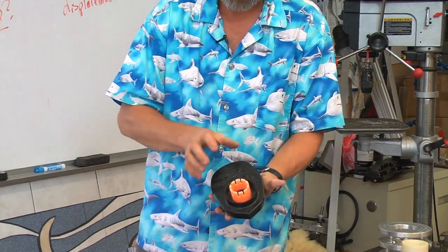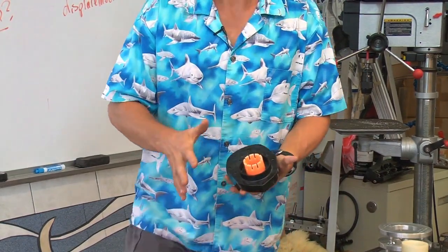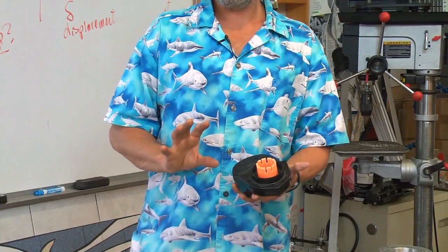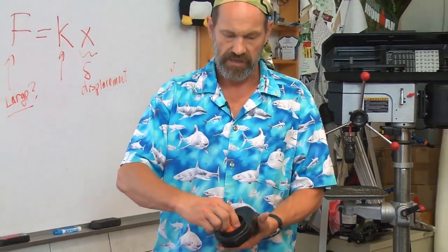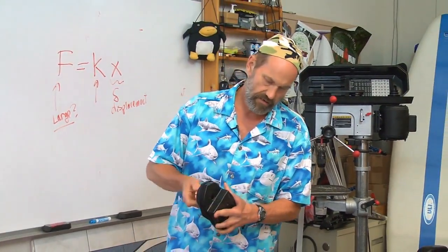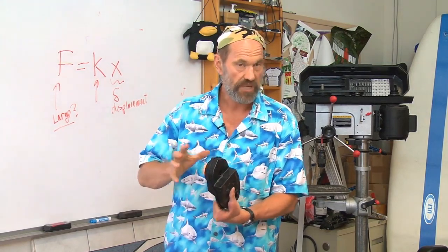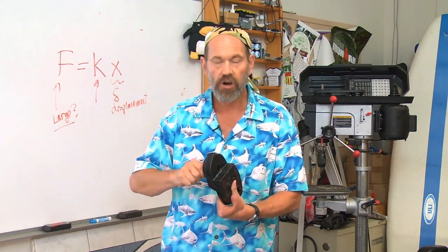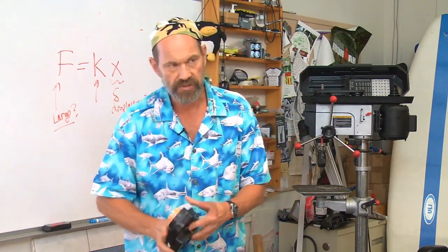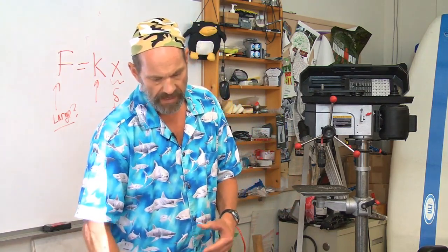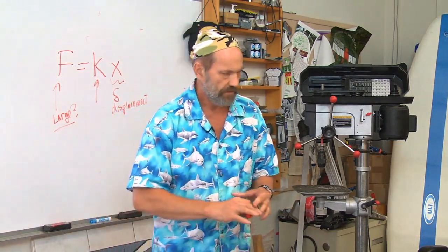So many different features, each with finite stiffness, is moving a little bit, and they all come to this minimum energy position that then allows it to function very nicely. So with, quote, cheap, flimsy plastic parts, you can often get, when they're put together, a cheap, robust design. It's all a matter of how you use the machine elements, and not just from the philosophical